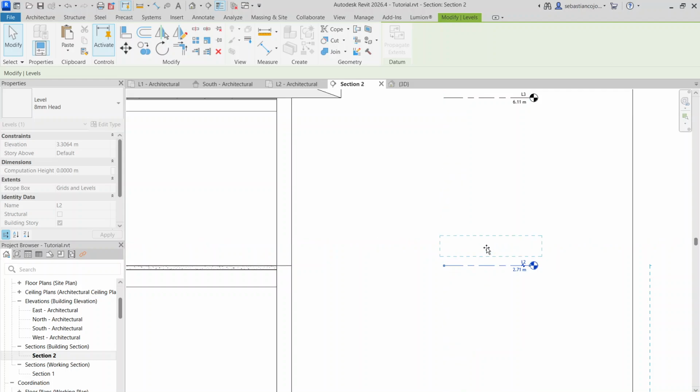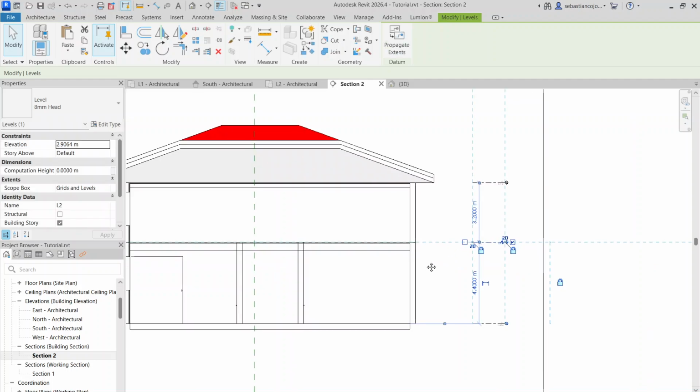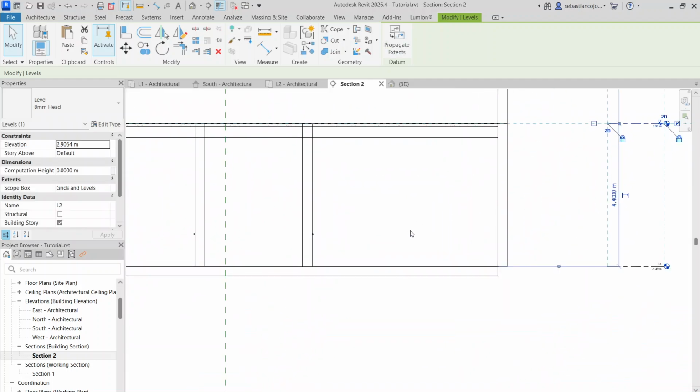Let's say I have 3 meters. Normally, between the beam and the slab, I would have 2.55 meters, something like that. The beam is, depending on the length, like 6 meters or something like that. And the height of the beam would be, I don't know, 60 centimeters or something.